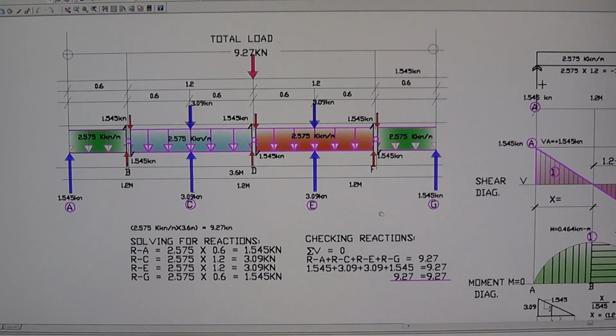Okay, now here's the loaded Purlin. In every midspan of the Purlin, right here between these two reactions and these reactions, in between at the midspan, you have to install the hinge. When there is a hinge installed, that is the point considered to have a 0 moment. Therefore, that's the point where we can divide the Purlin.